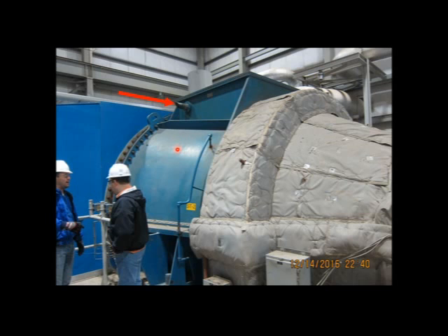One side of the bearing is at atmospheric pressure, and typically this vent should be spitting out a little bit of warm air or steam, but it was actually pulling in a lot of air. So there was a leakage through that bearing. That's where the air in-leakage was. Now that bearing also has a drain at the bottom down below the condenser. And so air in-leakage was coming in here and at the drain down at the ground level. We ended up bagging both of them to temporarily shut off the air in-leakage until they could completely fix the problem.